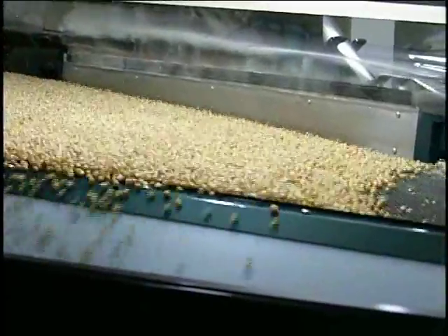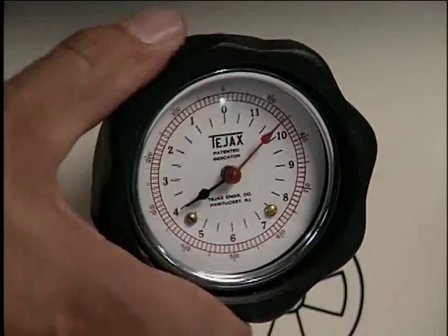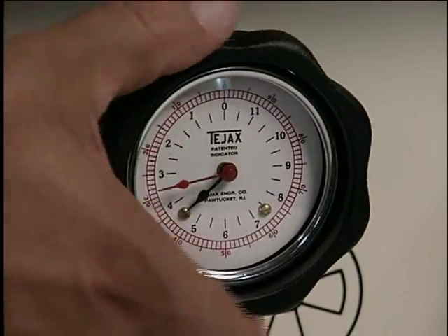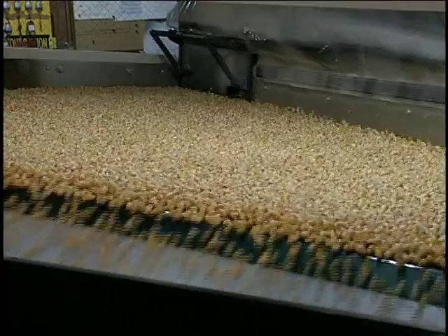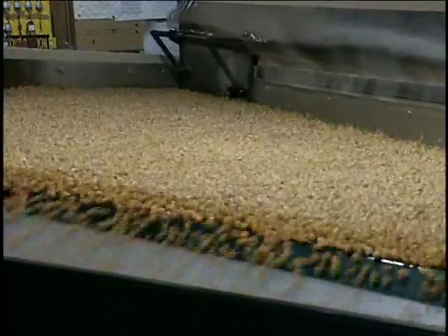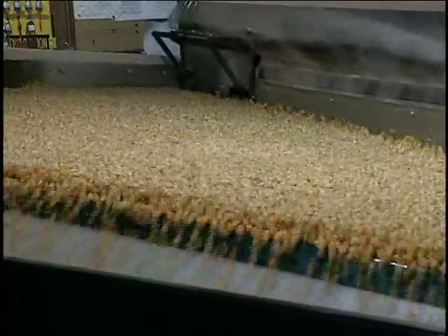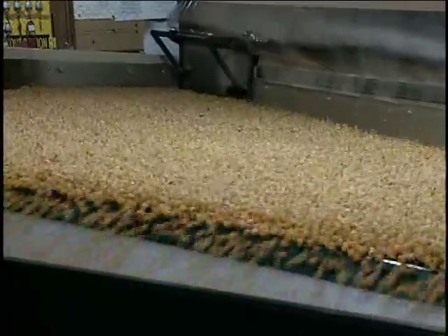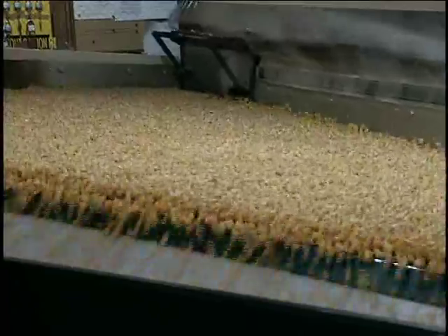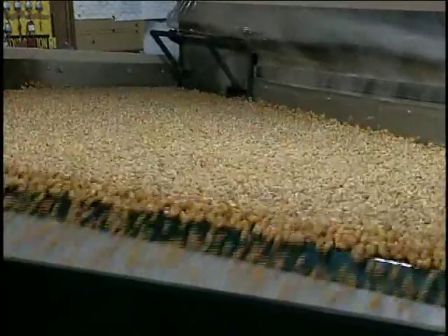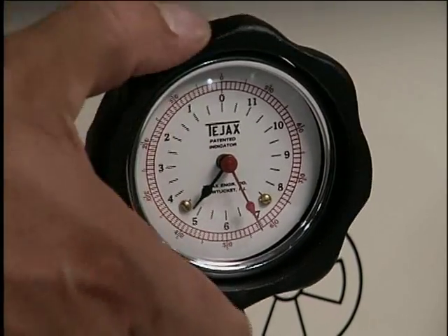Your first priority should be to adjust the airflow to achieve proper stratification. This is a prerequisite for maximizing the performance of the gravity table. As the deck fills with product, adjust the airflow so that the material is properly fluidized and stratified. Note that it is not necessary for the deck to be covered before starting this adjustment. Due to the unique design of the deck, material will fluidize even without complete coverage. Remember that the proper air setting will cause material to fluidize and stratify almost immediately upon entering the deck.